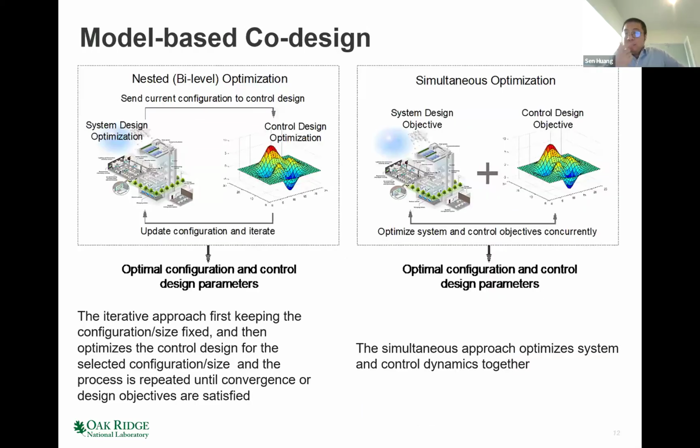To support this kind of activity, one question is always, as I mentioned, how we make sure the model is able to adjust based on the design. To achieve that, I utilize the modules from the Buildings library to create a model template for the chiller plant. I utilize Modelica as the key modeling technology, and we make the Modelica model a template which can take parameters as input.